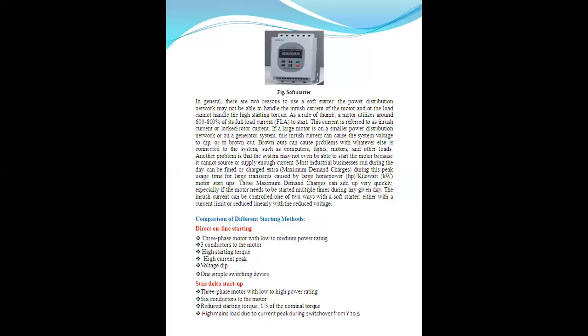Most industrial businesses running during the day can be fined or charged extra, that is the maximum demand charge during peak usage time, for large transients caused by large horsepower, that is kilowatt, motor startups. So the maximum demand charges can add up very quickly, especially if the motor needs to be started multiple times during any given day.